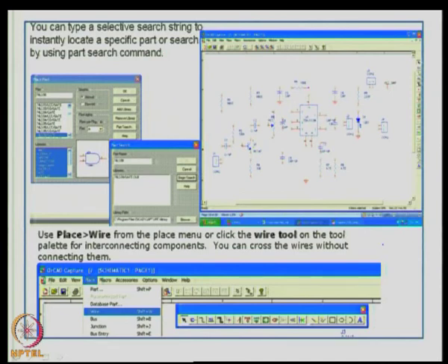And then as you can see here in this particular screen capture, various devices have been brought. They have been placed around the active device in a particular fashion, and the criterion for placing the other devices around the microprocessor or the active device is that the length of the interconnections to the adjoining part has to be a deciding factor, because ultimately in a schematic or your final CAD layout, you will see that the interconnection length will be kept to a minimum.